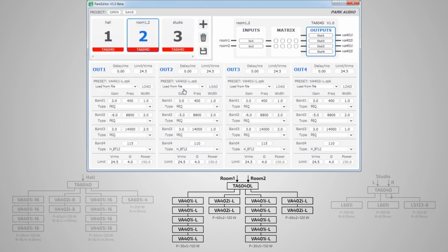In this case, we use a device with 100-volt output and acoustic system with 100-volt transformers. The acoustic system power handling matches the 100-volt line transformers, so no additional limiting is required. Therefore, the limiters remain open and we do not work with them.